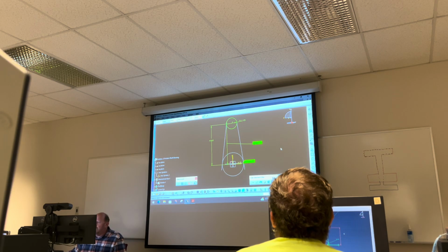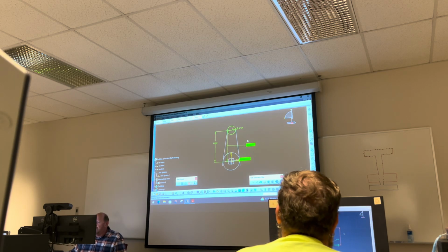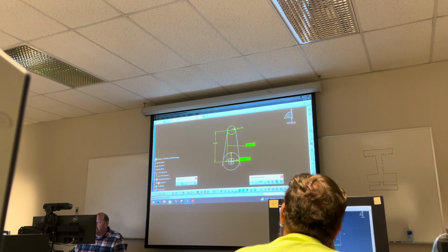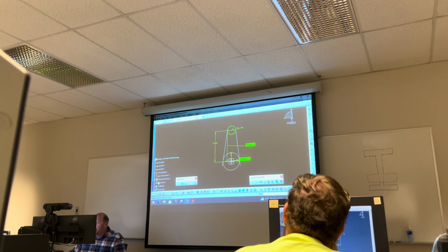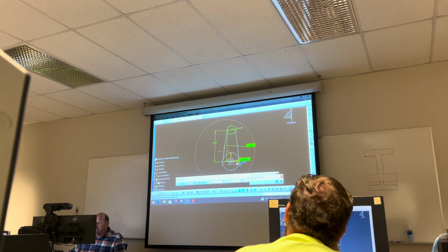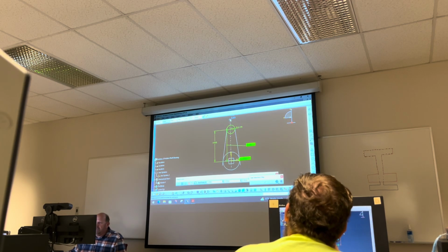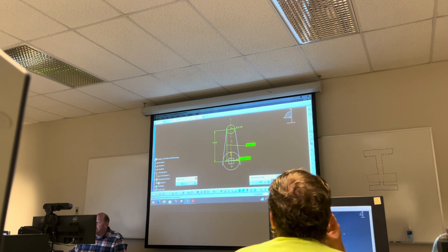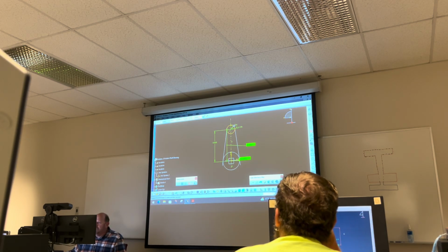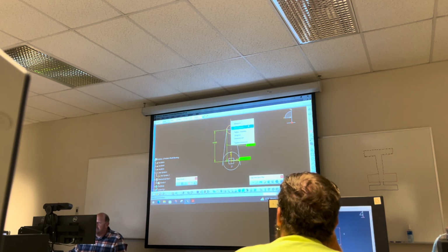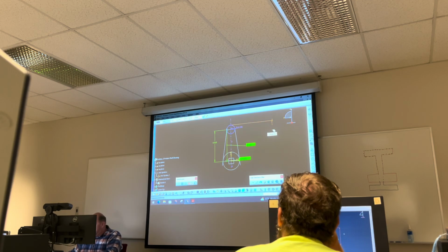It's not going anywhere. If I want to make sure that it doesn't move from side to side, right now it looks like it's concentric about this. It's got a value. I'll put an axis in here and make this coincident to it, but it should be locked. Let's see if it goes. Yeah, it's gonna go over constrained anyway, so this is good. So it shouldn't move.